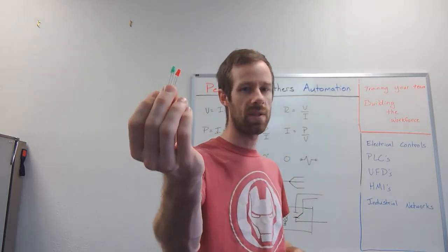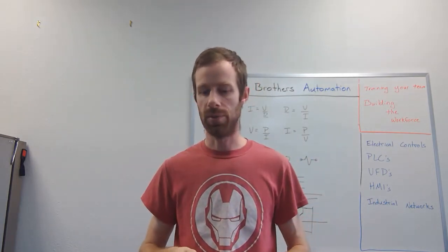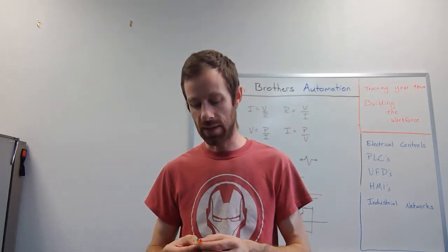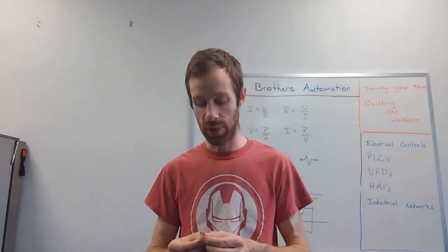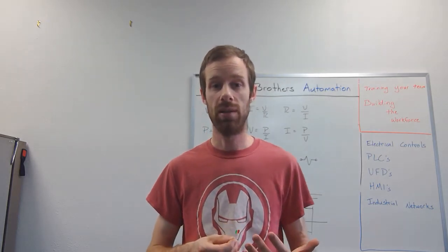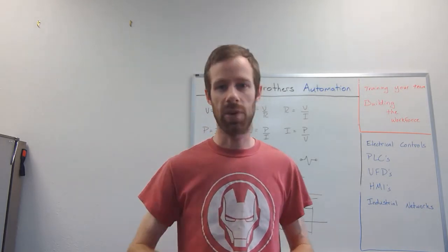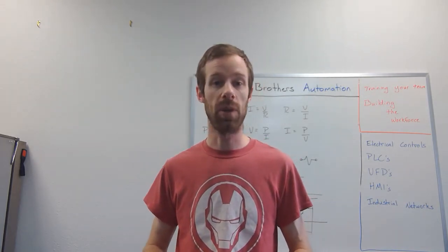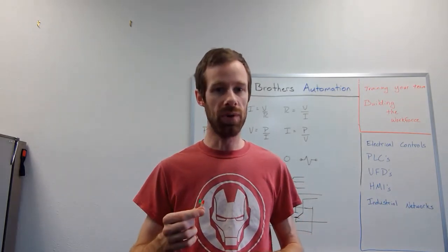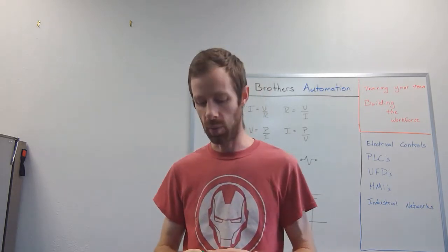So for those, I'm going to stick with the parts that are big enough for me to bend the wires and stick them into battery terminals or a breadboard to be able to connect. Make it easy. Those surface mount devices are cheap. They're mass produced, so they're very easy for a machine to install if you're going to be selling thousands of a board. But if you're just experimenting, stick with the other stuff. Instead of surface mount, we call these through-hole. If you do a lot of electrical experimenting, through-hole devices are the ones that we can connect to just about anything we want.